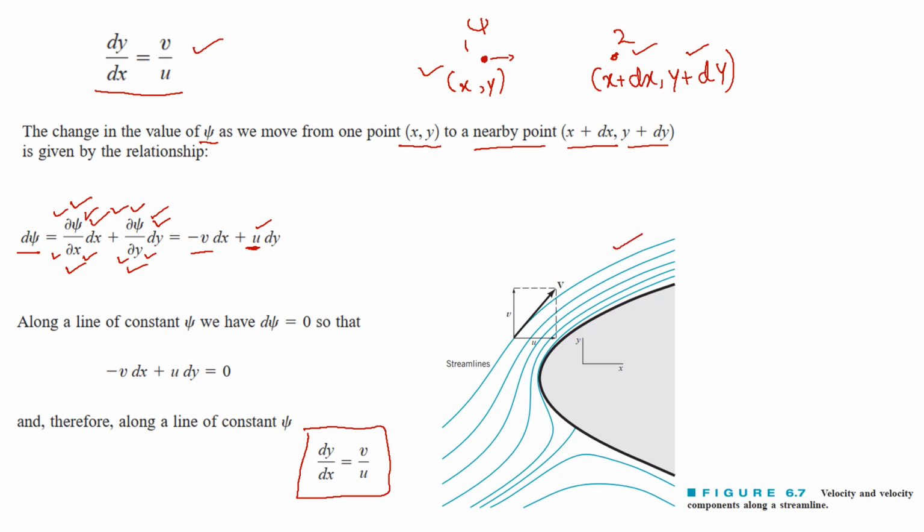As you can see in this figure, how that fluid will behave, and we can only see that with the help of these streamlines. And we can plot these streamlines by taking psi equal to a constant along them. So by applying this condition on these lines, we will be plotting our streamlines, and we will get a better visual representation of our flow.